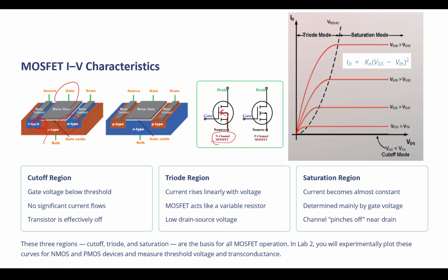The current is the current that goes through the two terminals, which you're lucky because they are in series. When they conduct, the current in the source and drain is the same. So if we consider the current of the drain, we are considering the current behavior of the whole main part of our transistor.